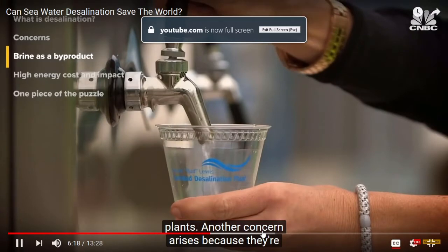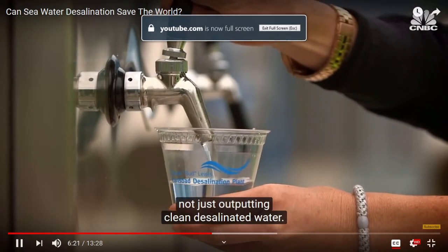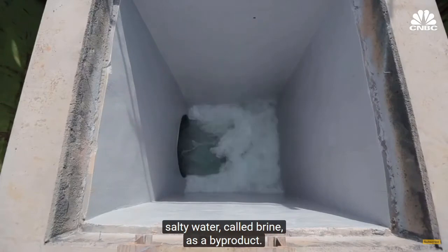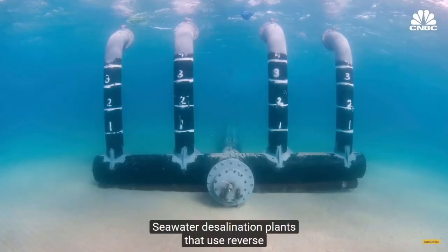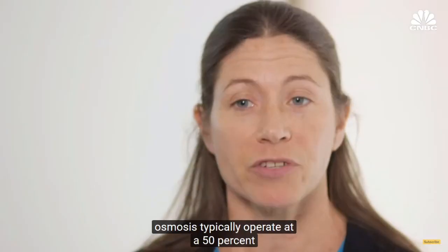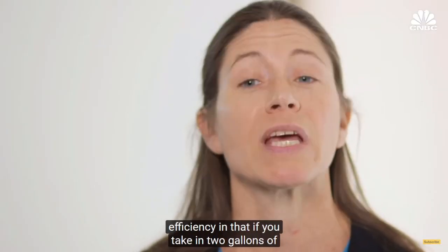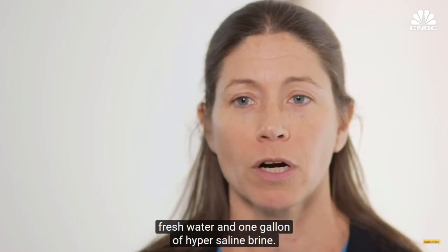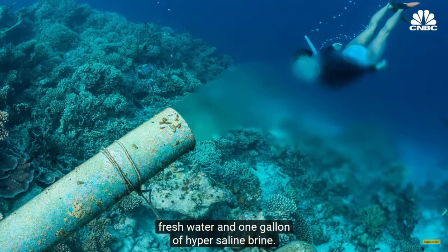Because they're not just outputting clean, desalinated water. They're also producing huge amounts of hyper salty water called brine as a byproduct. Seawater desalination plants that use reverse osmosis typically operate at a 50% efficiency, in that if you take in 2 gallons of seawater, you're going to produce 1 gallon of fresh water and 1 gallon of hypersaline brine.